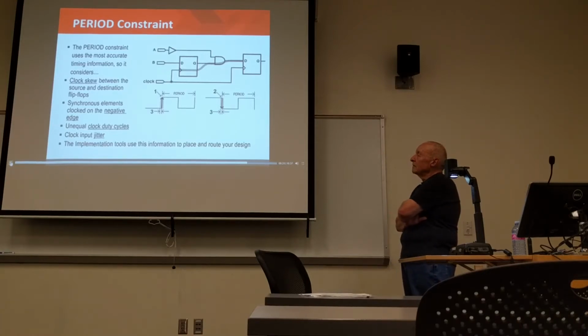So all of these factors are built into the implementation tools when completing a static timing analysis, and that's done for each iteration. Remember, you may have to do multiple iterations depending upon your speed grade and how tight your timing objectives are. Don't forget that all this may have to be completed many, many times to find a place and route solution that will meet all your timing needs. Suddenly, now you have a great deal of respect for the ISE software.